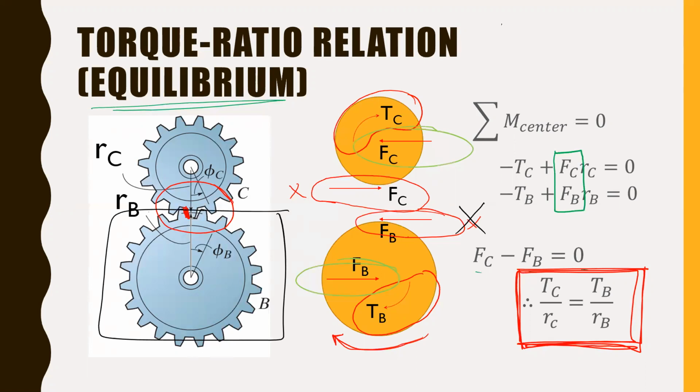So that reaction that is resisting the torque causes another reaction at the center of that gear, on whatever shaft it's attached to. That reaction is then causing bending in your shaft. So you're going to have not only torque, but bending. We're not going to talk any more about that today, but in a few lectures, we will design shafts, in which case you have to look at both bending and torsion. Okay, any other questions about the torque ratio? Okay.